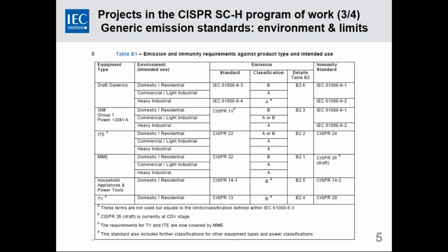and some of it for the ISM is based on connecting to the mains, the low voltage mains, and it has nothing to do with residential or commercial or light industrial, which is quite different than CISPR 32 or multimedia, which is based on a residential environment being something within 3 meters away, and a Class A being 10 meters away.